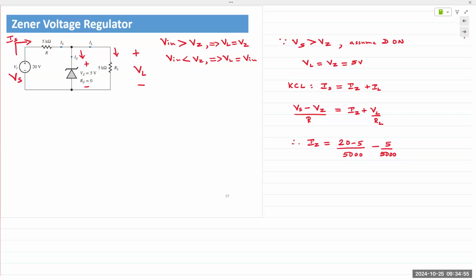Wait, let me take that back. It's not the Arduino. There is a voltage regulator board that comes with the Arduino as part of the kit. Okay, so we would plug our 9-volt source into that board, and the output of that board can go into the Arduino. It should just work. To plug in where though? No, in the USB port.